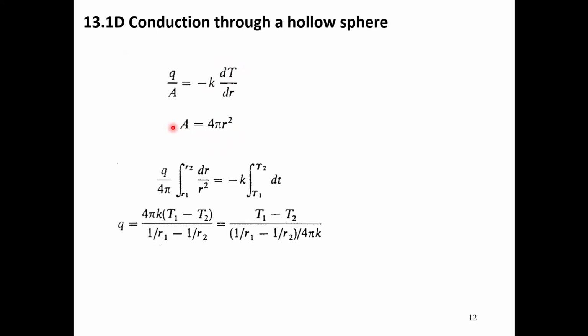And hollow spheres have importance in industries as storage vessels. When you look at a hollow sphere, unlike a cylindrical vessel where there is a sudden change from one shape to the other, so you will have points of weakness, in a hollow sphere it seamlessly moves around, and the pressure is distributed equally throughout, and therefore you won't have points of weakness. So when you want to store fluids that can lead to a high pressure and damage the vessel, in such scenarios hollow spheres are preferred.